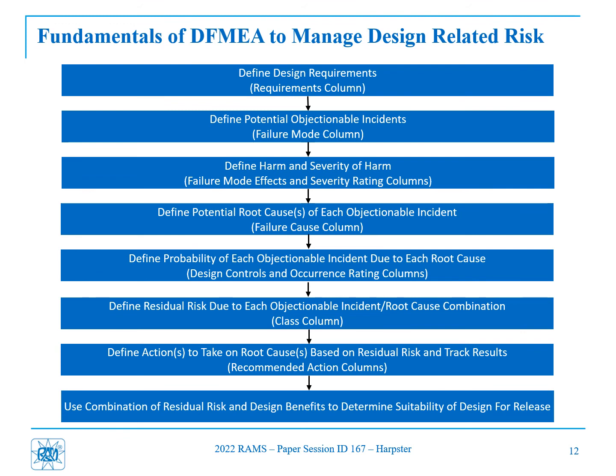And when you do have that symbol, that means that row of the FMEA represents objectionable risk. What we then do is, any row of the FMEA that has a symbol, we now know we have to work on. So based on the presence of a symbol in the class column, we then do recommended actions. We monitor those recommended actions and we monitor the changes in severity and occurrence. And if they go down and make the symbol go away, then we know we remove that residual risk.